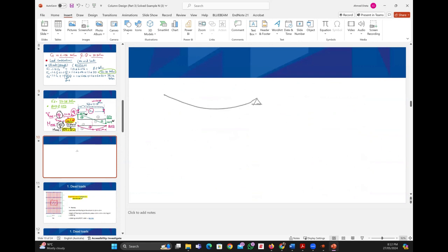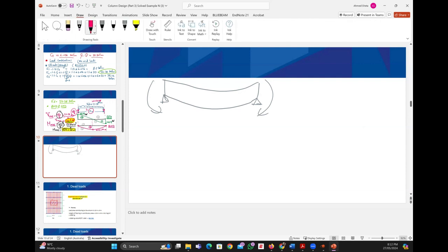The idea is, when you bend a beam, which side of the beam will be under tension and which side under compression? The bottom side of the beam will be under tension. The top side of the beam will be under compression. That's why, to make it easier, they put the positive moment on the tension side. So that's why below the datum is positive. Okay, thank you. No worries.